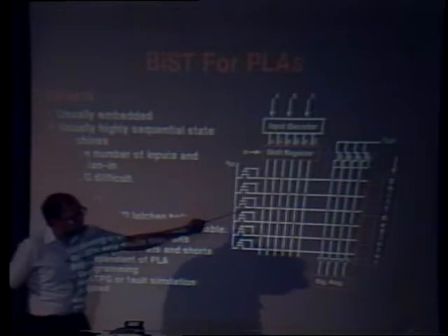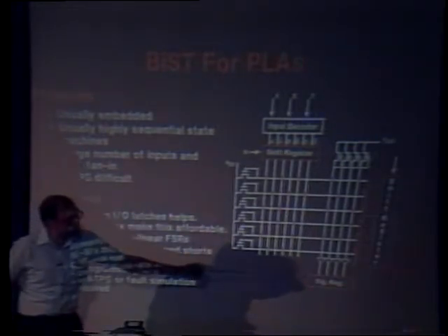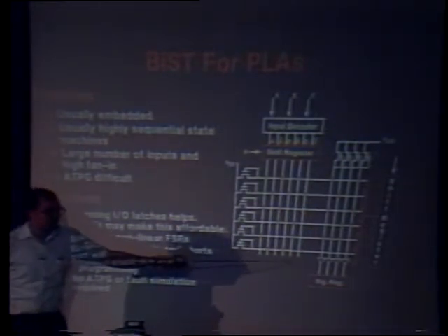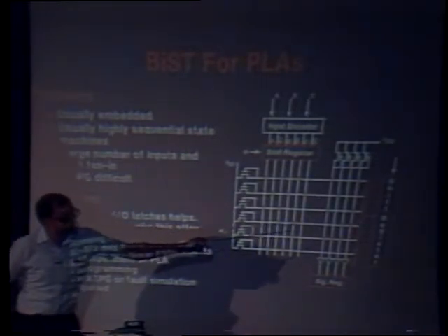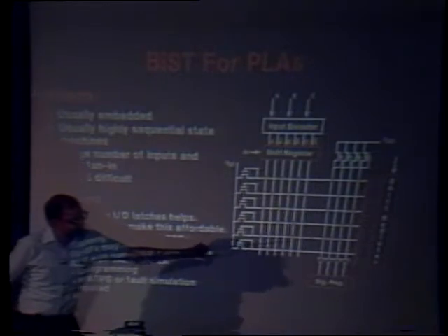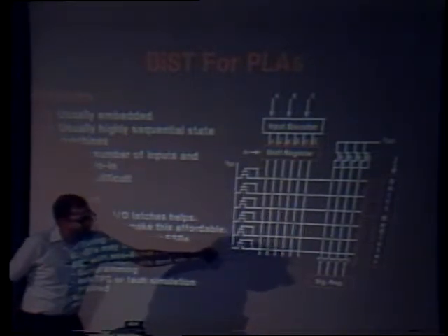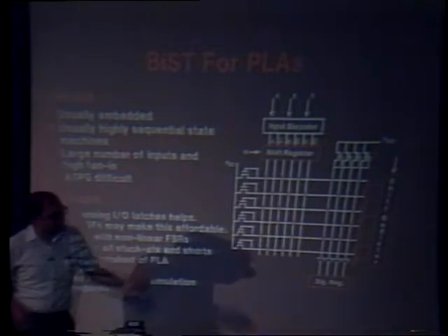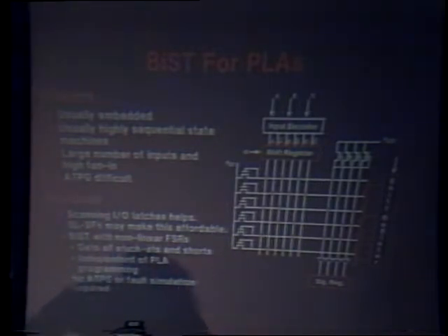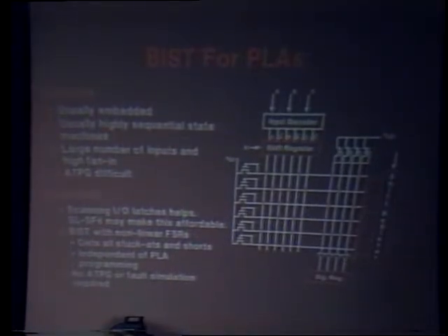After doing that, we have to sensitize the faults to the output where we can really detect the faults. So for that, we have another shift register over there, which would sensitize 1 output line at a time, and you apply that algorithm repeatedly. Too bad that I won't be going into the detail of this, especially now. This slide was done several months ago. There is even a better way to do it.